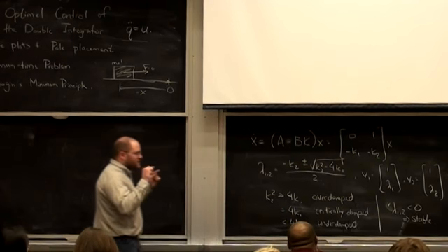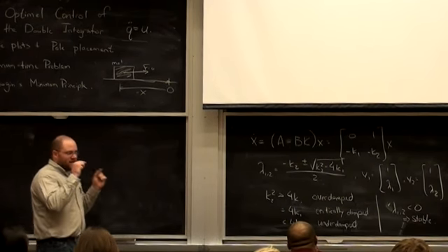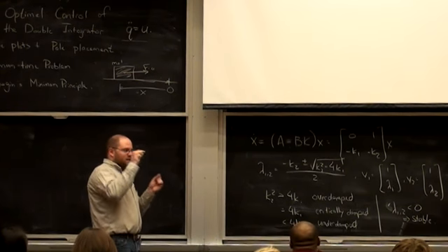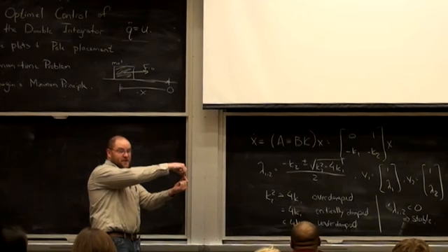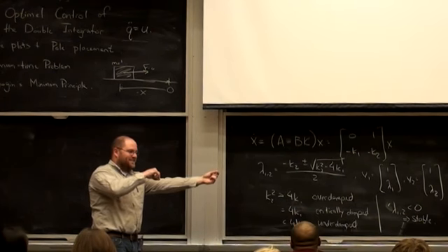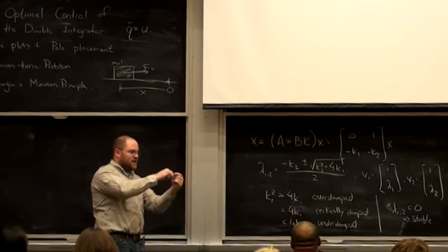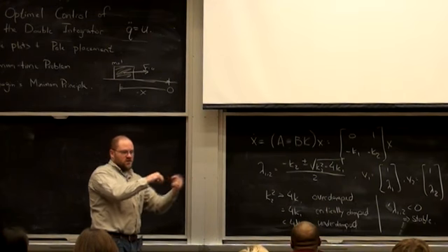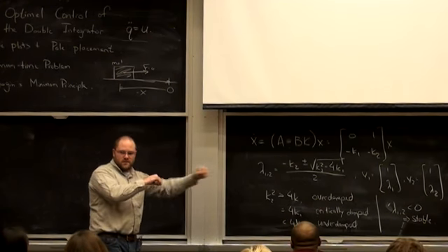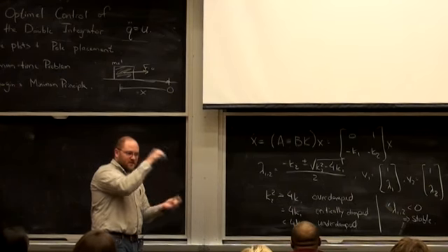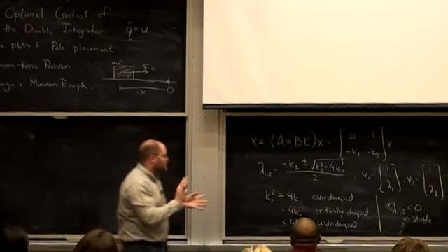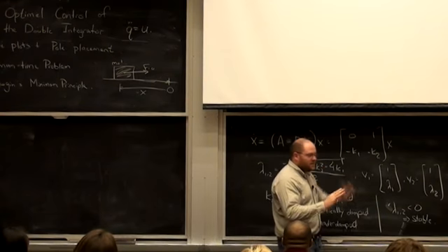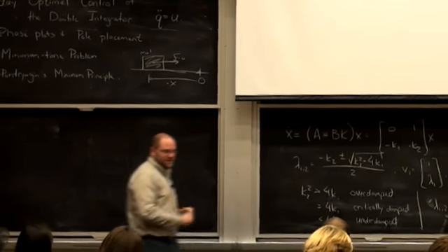So what you get is, for very small feedback gains, you get oscillations. As you crank it up, the poles connect in the left half plane, and then they separate, right? And as I keep turning up my gains, one of them creeps towards the origin, the other one goes off really far to infinity. So for those of you who think about poles and zeros, this is exactly the same way to say that. I didn't do a root locus because I was changing two parameters, but it all connects, okay?